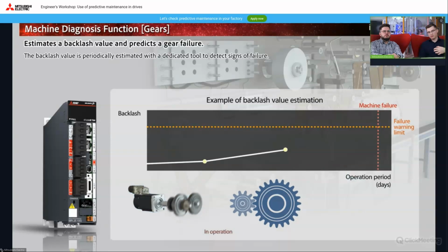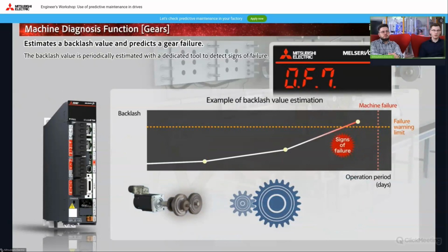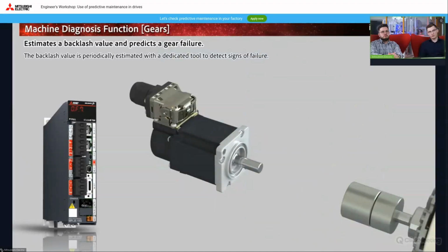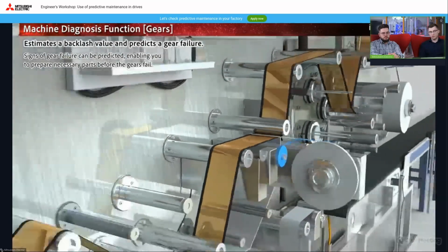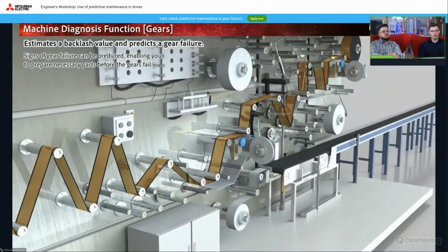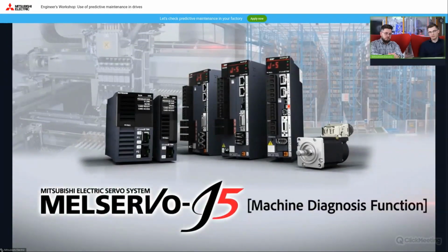After that, after some time, for example after a month, when the machine is not working and we are just starting the machine for, let's say, a new week, then we can always check via our software what the backlash is. Yes, and then after some time check again. And when this backlash is too big, then we'll think, okay, we will have to do the maintenance on this mechanical part and check what it is about. For example, replace it later. Yes. So let's see how it works, how it looks like in reality.